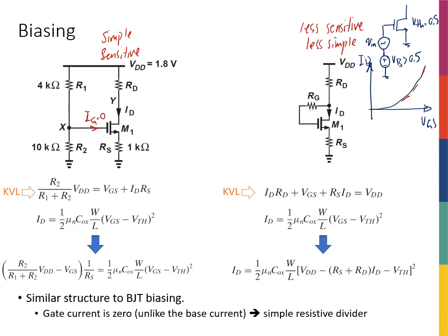Remember, when we build a transistor, we said that I have an oxide layer, which was an insulator, and on top of that I put the gate, right? Unlike the drain and source, which were connected to some metallic contact, the gate was connected through this capacitor. It had a metallic or poly contact on the top, but then there was this insulator here, so there's no way that we have a DC current flowing through the gate. Why is that good? Because now, without any approximation, I can say with confidence that I1 and I2 are equal, simply because of KCL.